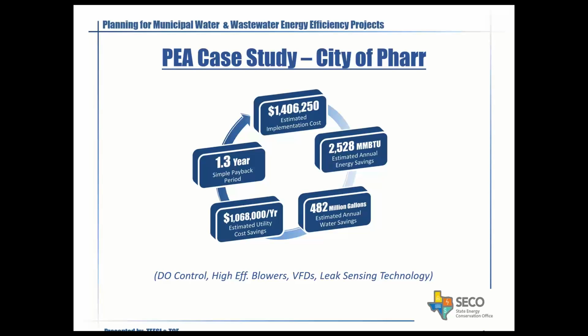That is correct, and I'll talk in general numbers again. Typically, when we're over 5% unaccounted, we're considered to have a problem. And now with this leak sensing technology, these meters can detect a water leak by hearing it and triangulating it between the leak sensors of the meters, and you can get within 10 feet of where your water leak is, just by your computers analyzing the triangulation of the leak sensing technology. So that's a pretty slick way of finding a leak.